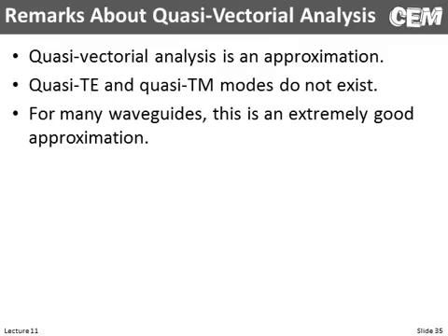This is one of the things when I was taking electromagnetics that drove me absolutely crazy, and I didn't understand it. And every time I asked the question, in hindsight now I know it's because the professor didn't understand it either, because all the textbooks just say, here's a waveguide, we're going to solve for the TM mode, and these field components are 0. And it's never justified why those are 0. And the answer is there is no justification. It has to come from a priori knowledge. We calculate the modes and see that they are very close to 0. But it is an approximation. But the textbooks don't present it as an approximation. They present it, this is a TE and this is the TM mode.